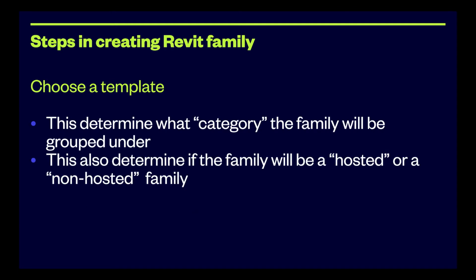Now with the steps. Step number 1 is to choose template. This will determine what category the family will be grouped under. This also determines if the family will be a hosted or non-hosted family. Now, it is important to choose your template carefully because if you decide that you want to change your family from hosted to non-hosted later on, that is not possible.